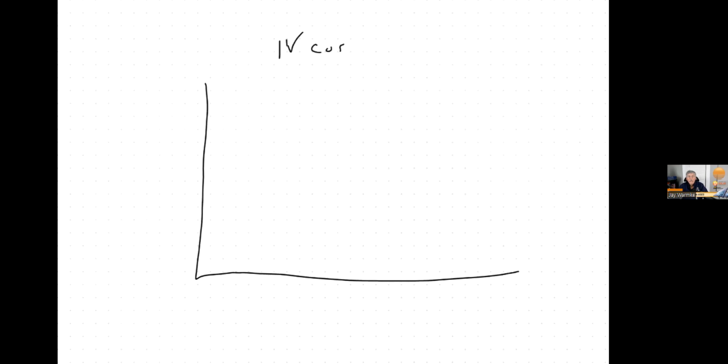This is a concept that some people struggle with, and it's really important that you understand. The idea of an IV curve. So this is an IV curve. IV just stands for amps and volts. And every solar panel will have an IV curve that looks something in the neighborhood of this. So what does that mean? Well, this is amps over here. It's a plot, and this is volts, and this is going to be zero axis.